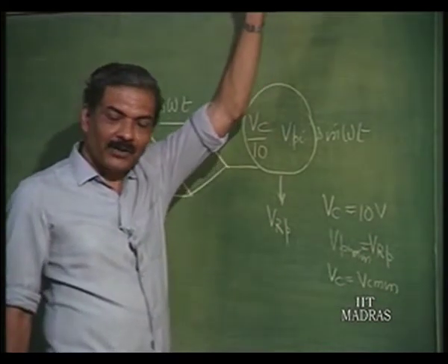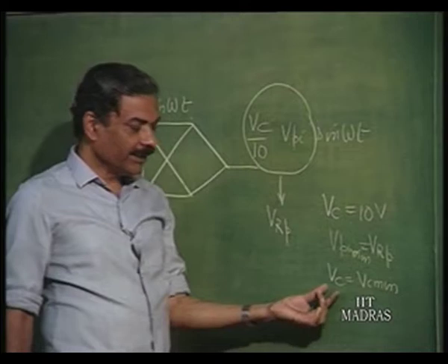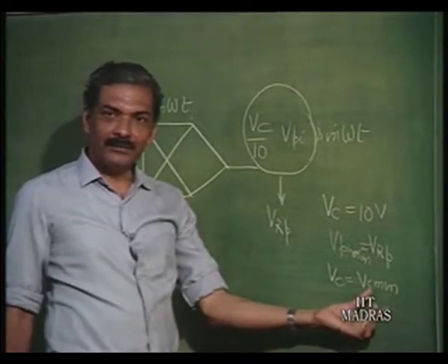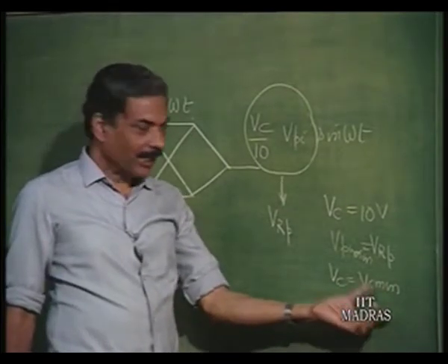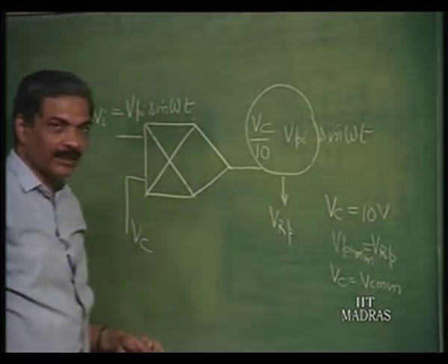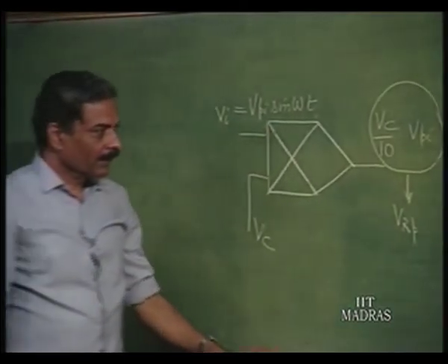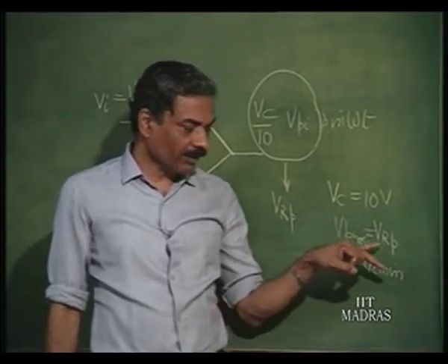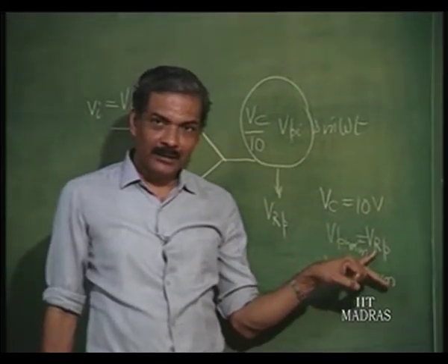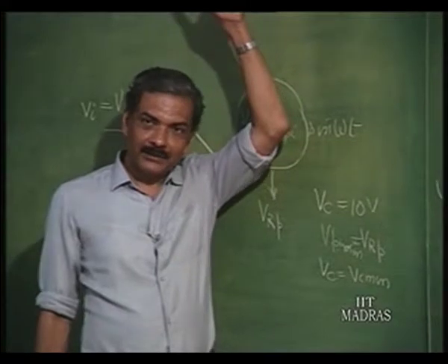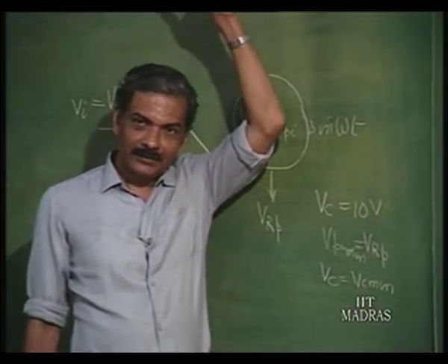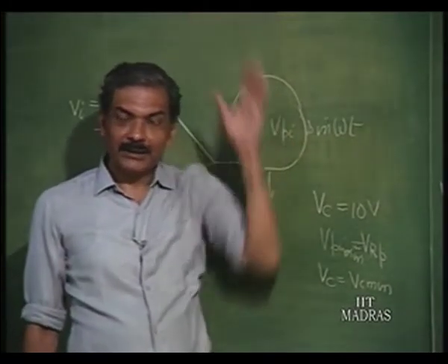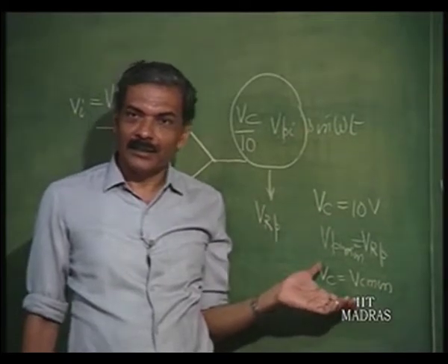So, for all those large values Vc can take on the minimum value. So, there is no problem. So, as far as this AGC system is concerned, it is going to work for a variation of voltage starting from Vrp up to very large values of the signal. Okay. This is because this is basically an attenuator, not really an amplifier.